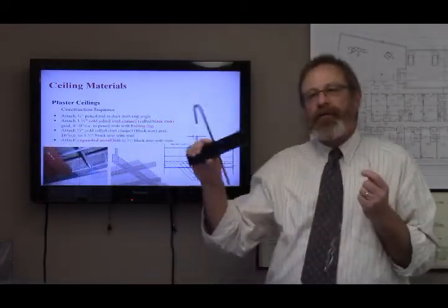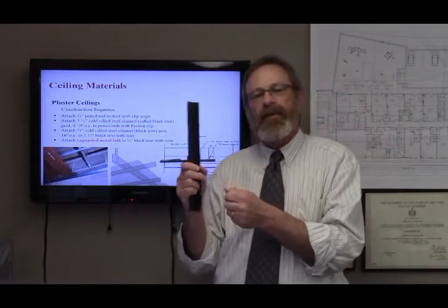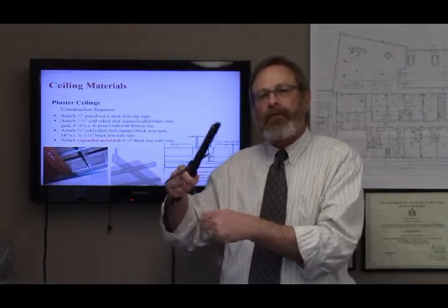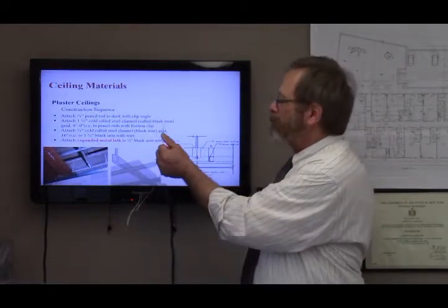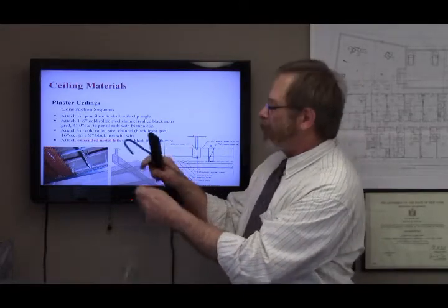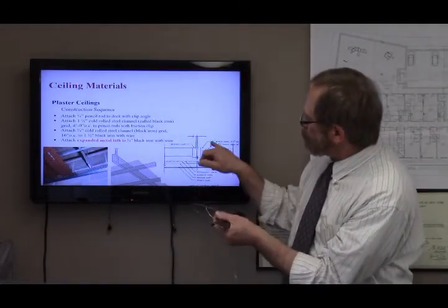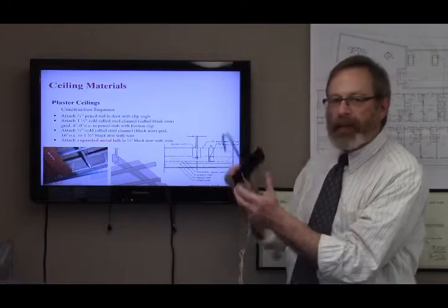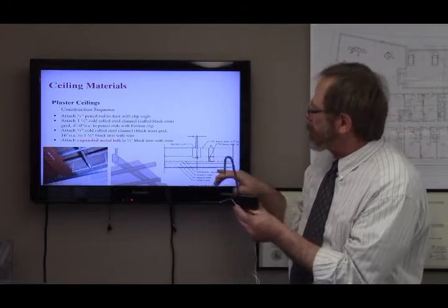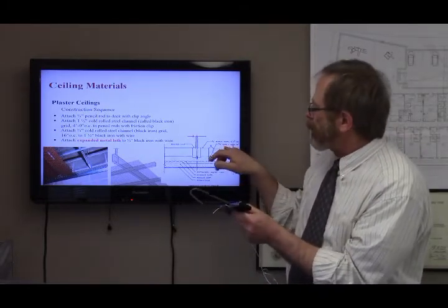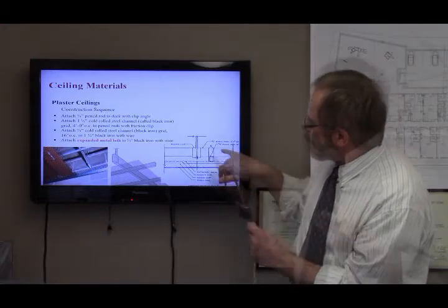To that 1.5 inch channel, we're going to tie a piece of malleable metal wire. This is similar to what we're talking about. And we're going to simply tie another channel to the bottom of this channel, half size, 3/4 inch. You can see it here.